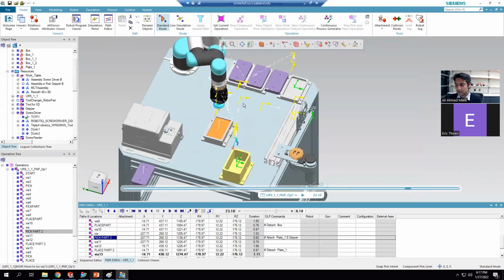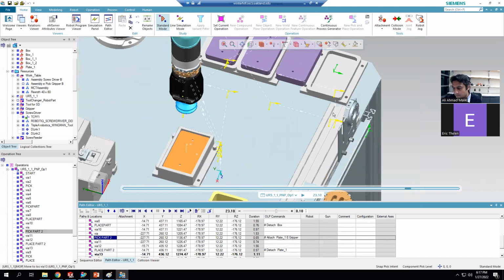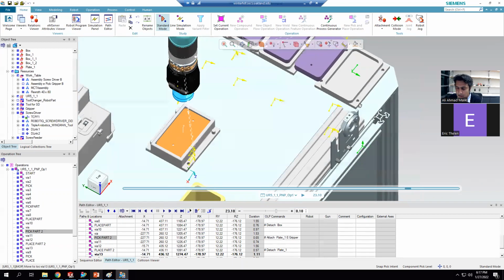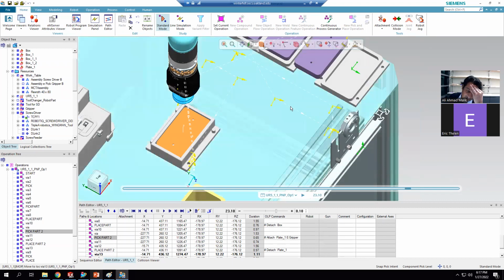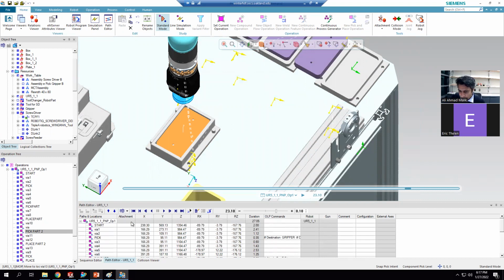Okay, so now we have to place this tool back to its position from where it had picked it. Ideally, you should copy the same locations. Also, when we are programming the real robot, we try to copy the same. Here you can find X, Y, Z positions. Either you can just note them down and copy and paste these so that the robot follows the same locations that it had used for picking the components, picking the tool, and for placing the tool. Basically it should follow the same XYZ locations.